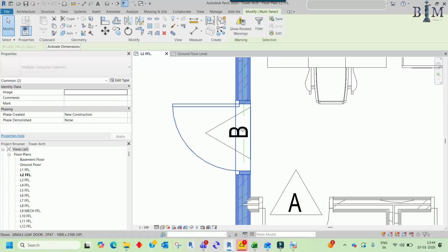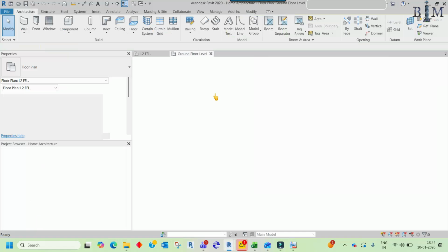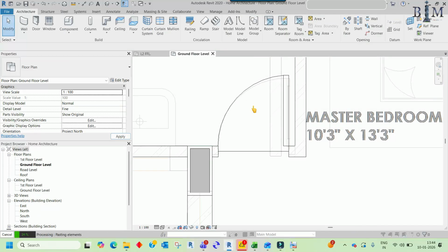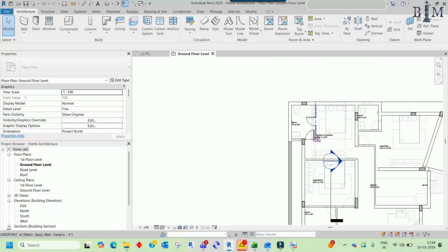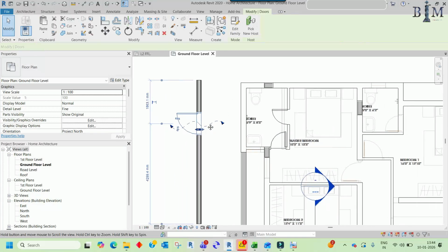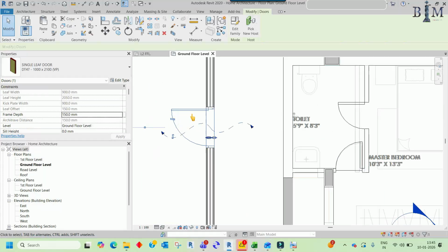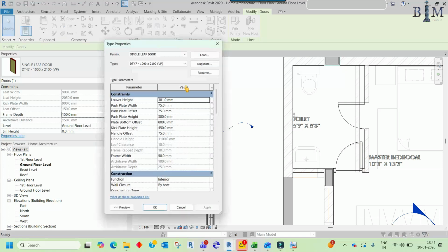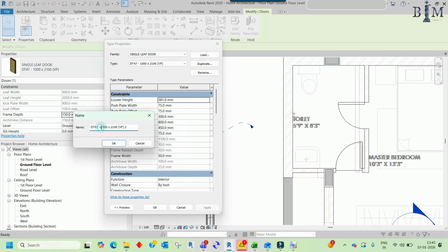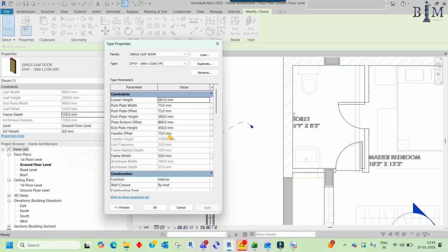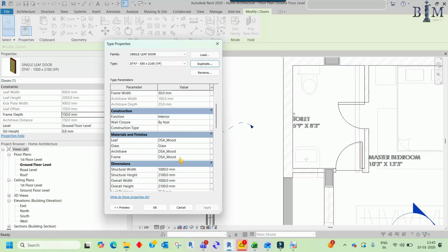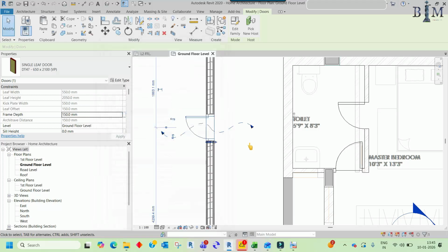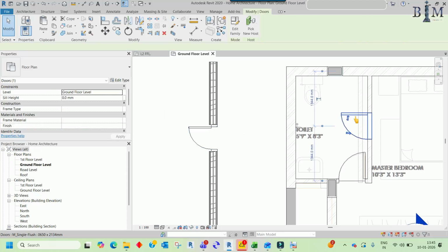In that case select the wall together, copy, and on the ground floor Control V and paste the wall here on the location. You can see the wall has been copied, so here you can edit the wall. Just select the wall, you know already, edit type and here duplicate, and it should be 650. Okay, so just VP I can take. Here I need another dimension with 650 and okay. Now you can see the door will be like this, so delete it and delete it.